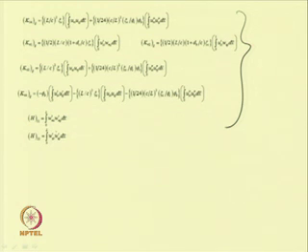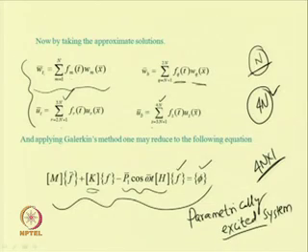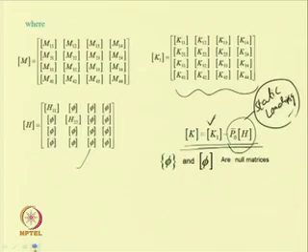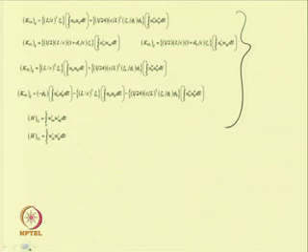So, here H11 can be written as integration of W'_mi into W'_mj dx bar, and this H22 equal to integration 0 to L W'_qi into W'_qj dx bar. Here it may be noted that we are using m for the top layer, q for the bottom layer, r and s for the axial deflection of the beam, while m and q are for the transverse deflection. In this way we can write the equation of motion and find these coefficients by using these integrals.